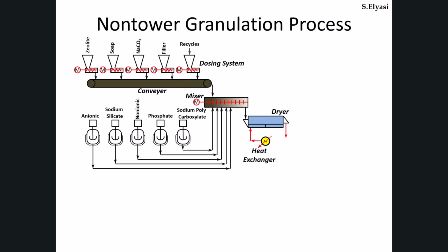This route supports high-density powder production because the material forms as a compact sheet or flake with fewer internal voids than many spray-dried particles. Density can be increased further through granulation and compaction downstream. Key control variables include film thickness, drum speed, residence time, steam pressure, temperature, condensate removal performance, and scraper alignment.